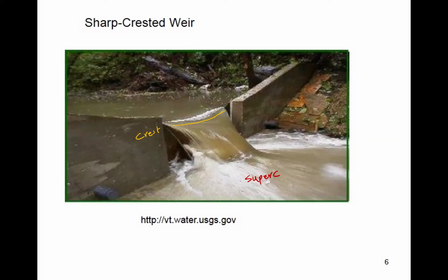So it might be more of an environmental type aspect of these structures. There could also be, I should mention, an application where you use these for stream control and erosion management and so on. Because as you can imagine, upstream, you're slowing the flow down and reducing the potential for scour.